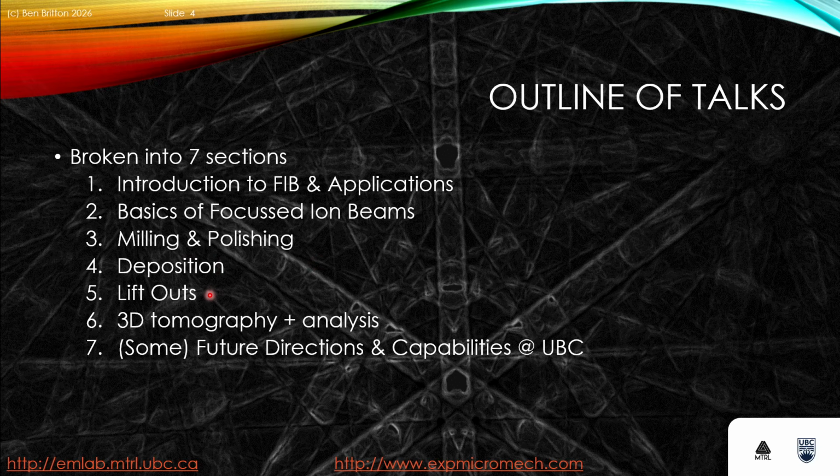We can then apply these approaches to enable us to do lift-outs, both TEM lamella, atom probe tomography, and tomographic work for, say, X-ray and electron methods. Then we're going to apply analytical FIB-SEM to do 3D tomography and analysis, and we're going to see how that works with some case studies and a full detail of how one experiment for a magnesium indent is performed. In lecture 7, there are some future directions.